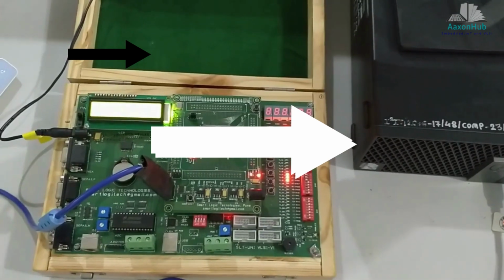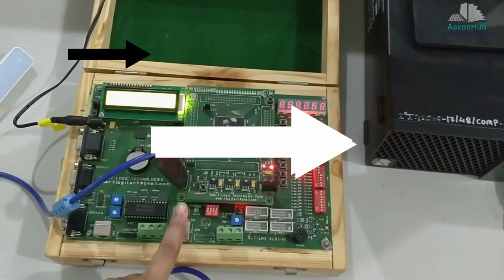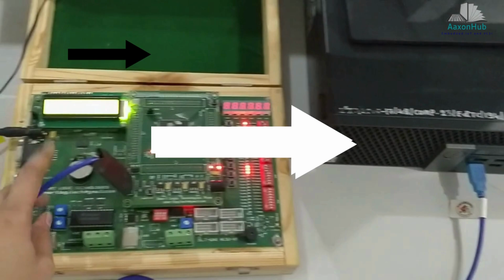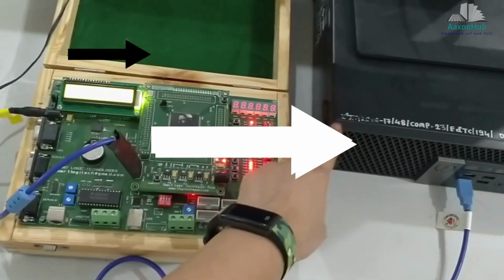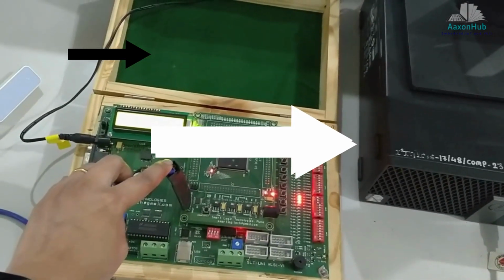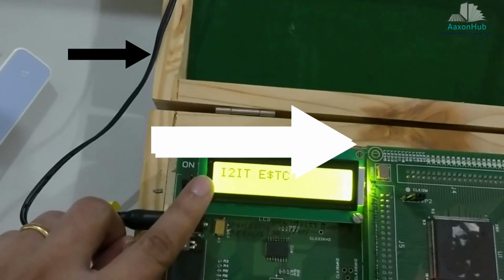Interfacing of LCD, you require Spartan-3E kit. Now this kit is connected with your PC using JTAG cable. So here is your JTAG connection. So using USB to JTAG connection interface is given from your PC to this Spartan-3E. Here is your LCD. Now this LCD is 16x2.